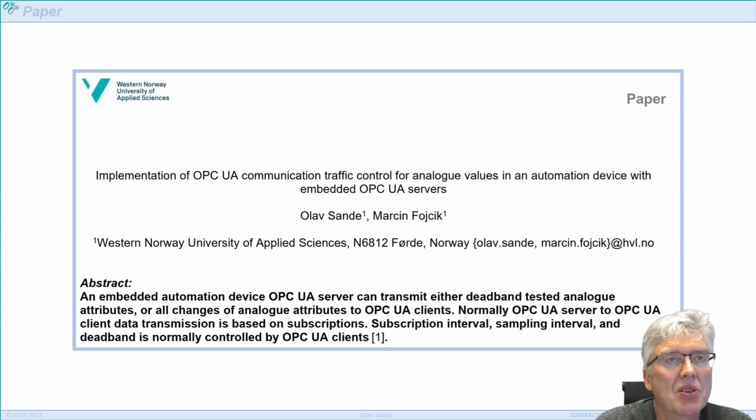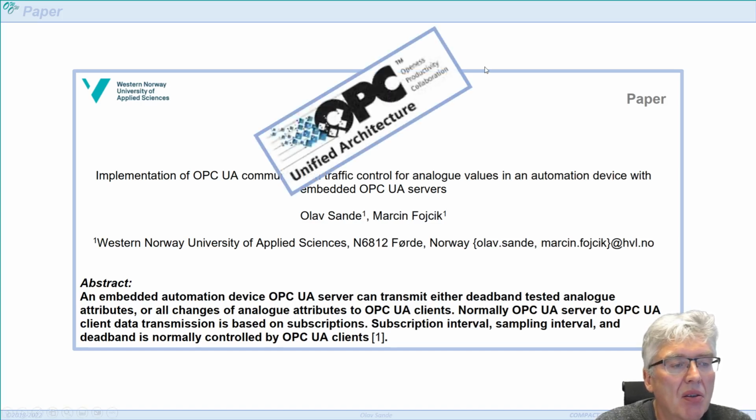So here the communication control is by the server side, and it is on OPC UA, which has been used exclusively in this system. OPC UA is a modern secure protocol which is also moving into time-sensitive information flow, which is not needed here because the time-sensitive processing is within the IPC system.